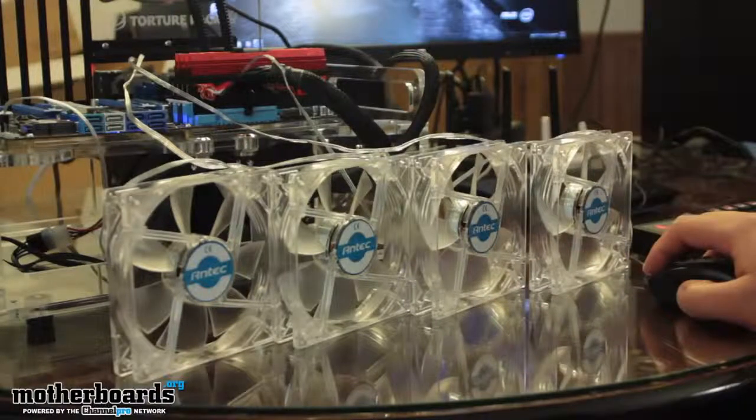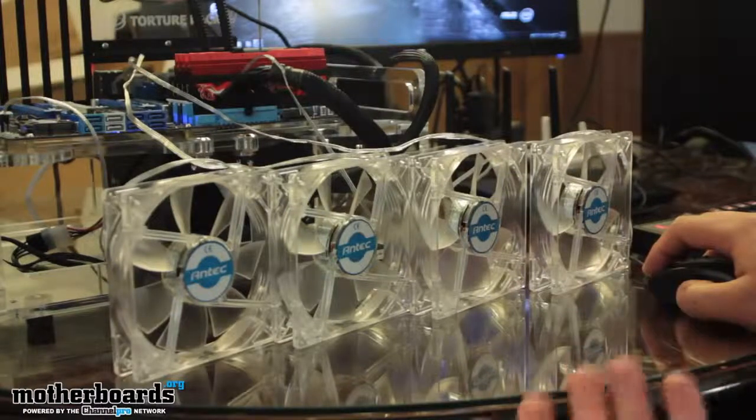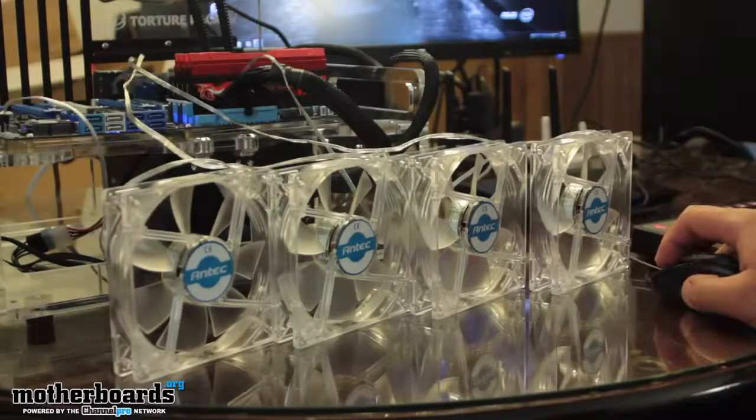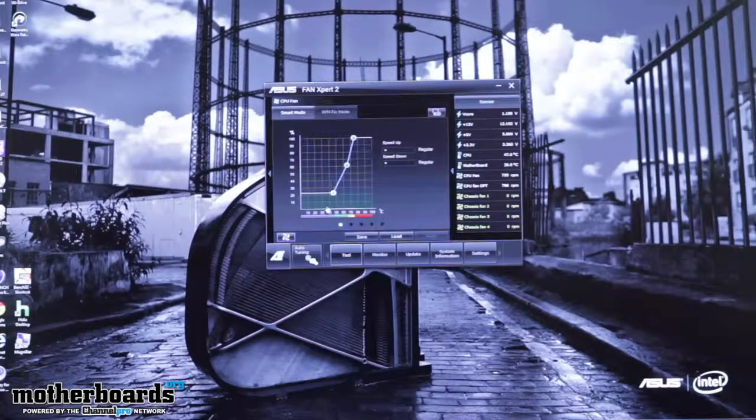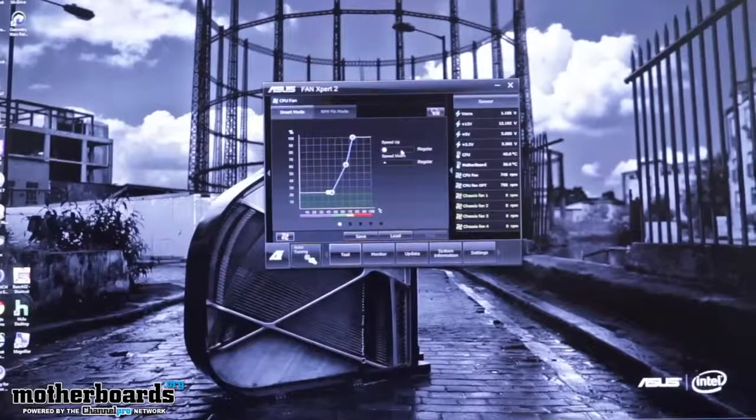Sure, but regardless of the configuration that you have, you're going to have the most flexibility at defining the characteristics of how to run your fan setup. So from that, let's go ahead and actually jump into the advanced mode interface. And we see right here, we even have a higher level of control. We can actually set a custom fan curve. So if you wanted to adjust at different points, you can adjust the rotation rate as well as when it's going to change based on the temperature. And we even have these options here called speed up and speed down. This is actually the aggressiveness at how fast the fan will make an adjustment.